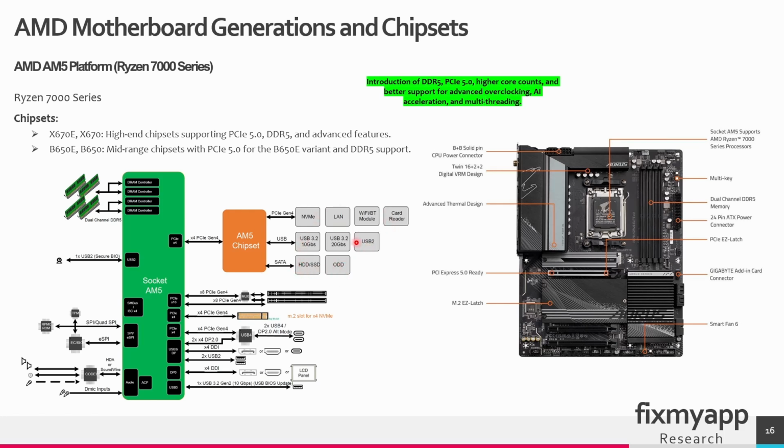So all the communication between those devices goes through the chipset and the CPU. The CPU itself has a PCIe controller built in and also a memory controller because it will interact with the DDR5 memory. The audio circuit communicates with the CPU, and also if you update the BIOS by USB, this data communication goes to the CPU.